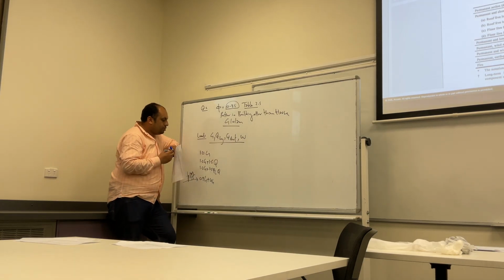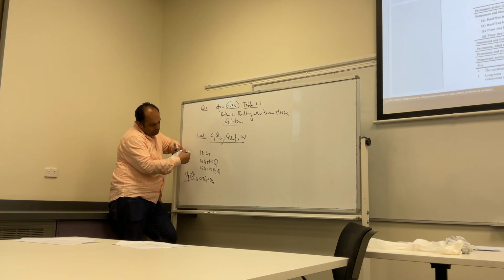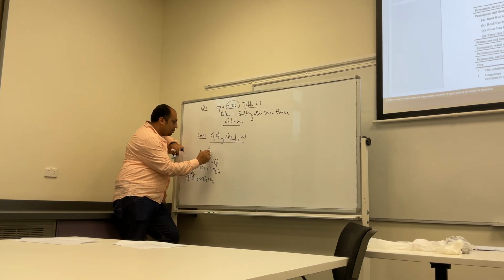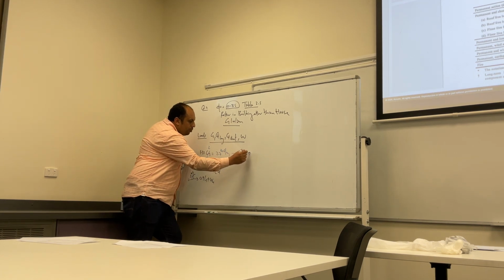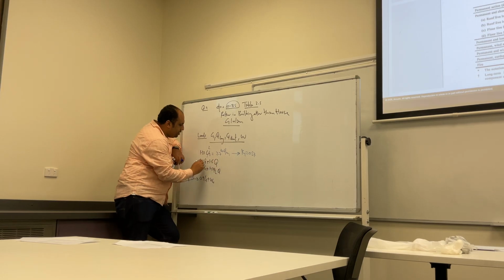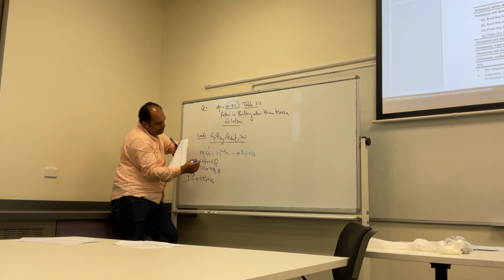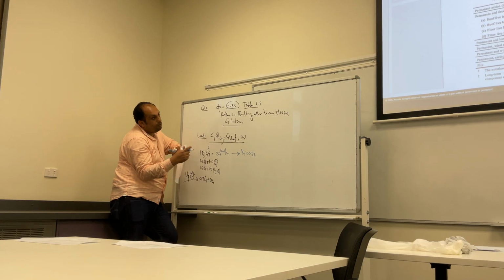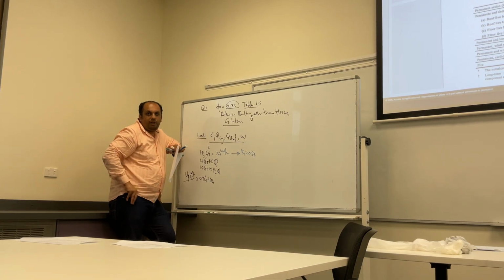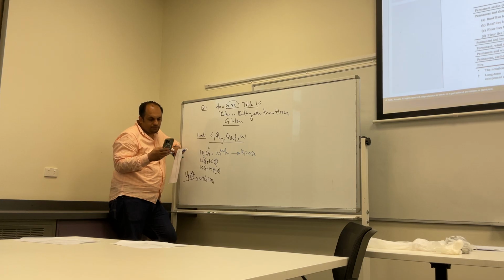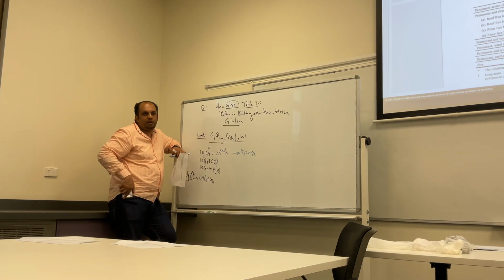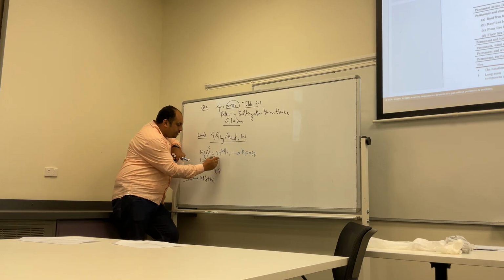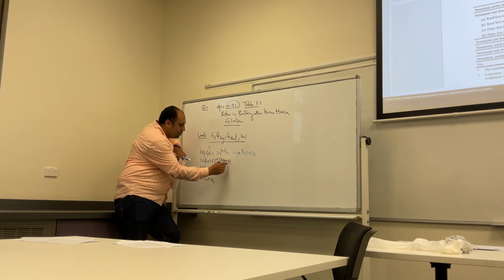So for the first one, how much is G? Given to us, G is 2, 2 kilonewtons per meter. So this is 2.7 kilonewtons per meter, right? What is the factor of K1? 0.53. For the second one, G is 2. How much is Q? 1.4, right? Because we have 0.6 and 0.8. Is that correct or not? You add them together, the Q's. Yeah, because this is the total live load. So Q here is 0.6 plus 0.8, or 1.4.